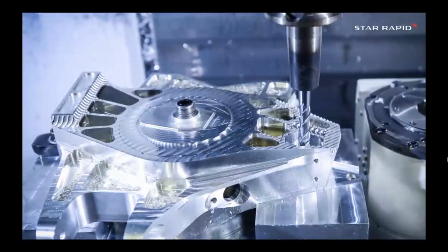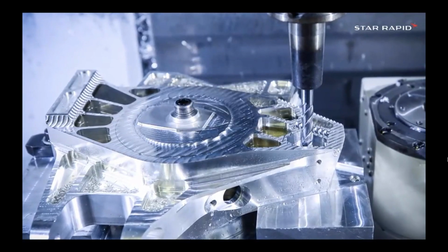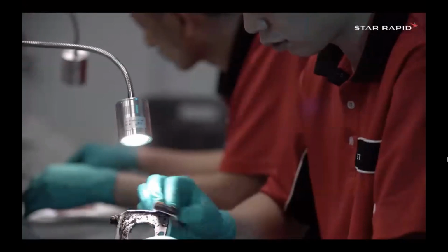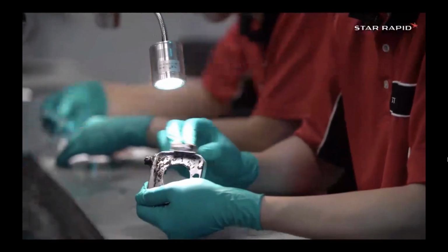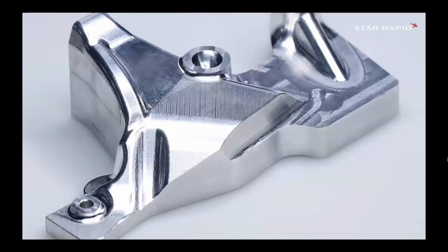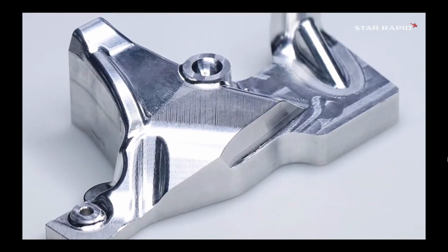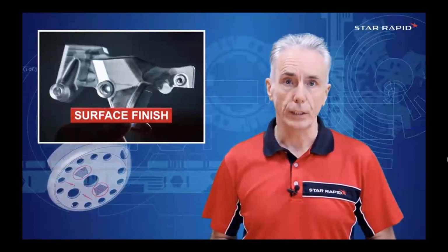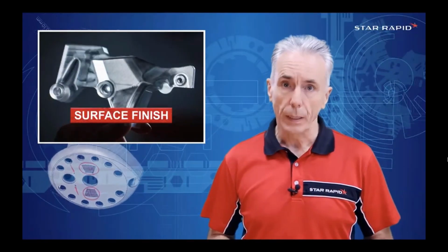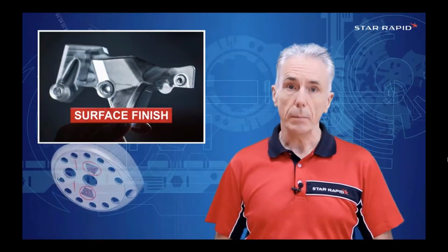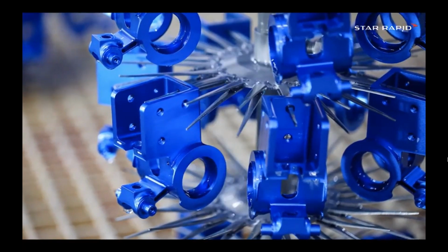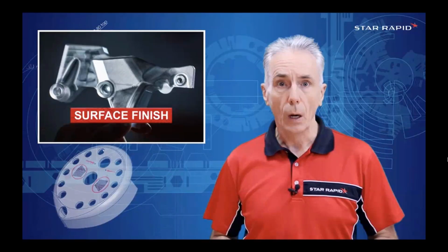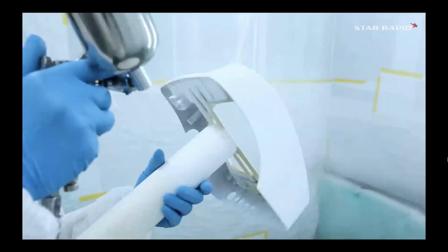Next, there are secondary surface finishes created during CNC milling, turning, grinding, sanding, lapping, or polishing. Each of these processes will impart its own characteristic finish to the surface, leaving behind a fingerprint of sorts on the workpiece. Then there are many flavors of tertiary finishes used by other treatments. Examples here: various chemical passivation techniques like anodizing or galvanizing, electroplating with chrome or nickel, or decorative surface coatings such as painting or powder coating.